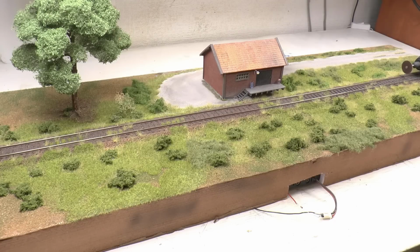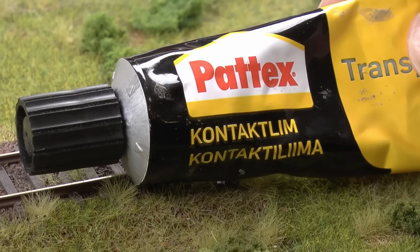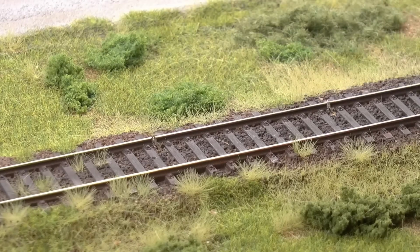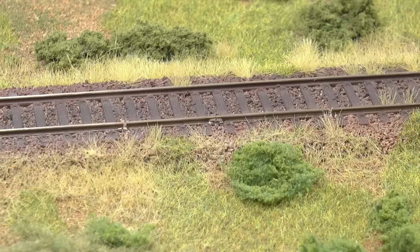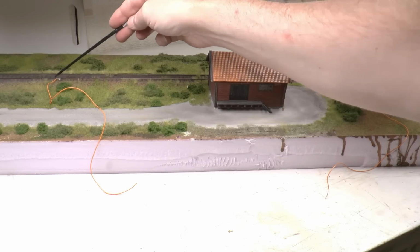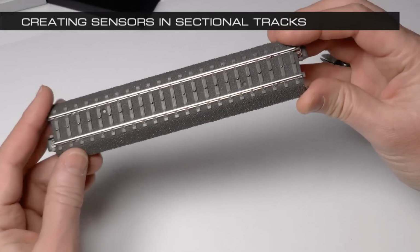Then to secure this slot and the isolation, I insert a drop of Patex glue into that slot the saw blade created. That will prevent the rail from moving with the train. Then it's just to solder a piece of wire to the rail, which is in turn connected to the feedback decoder. Now, working with sectional tracks is basically the same thing.